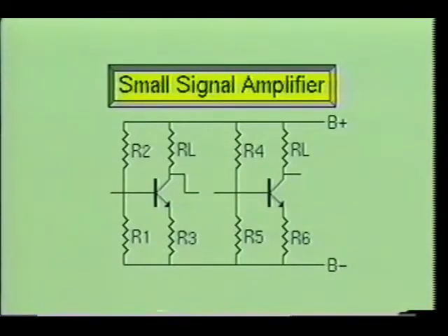Usually, small signal amplifiers are used for the first several stages of an amplifier system. Therefore, coupling networks are used between the different stages to transmit the modulated signal from one stage to the next without upsetting the bias of the individual stages.